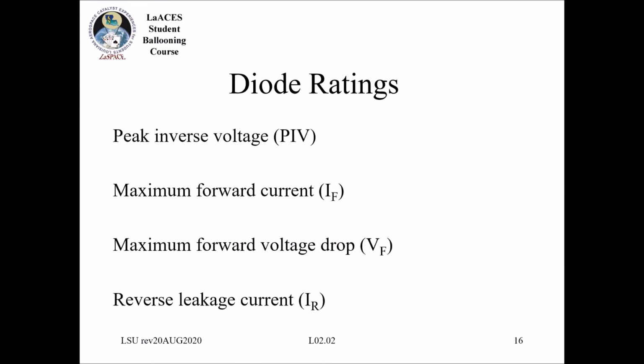And then back to your question, there are different ratings to keep in mind. Peak and burst voltage would be the maximum. Like we said, you can put this in backwards or have the negative voltage, but there is a maximum to that before the device will break down. So you definitely don't want to exceed that if you're using it in that way.